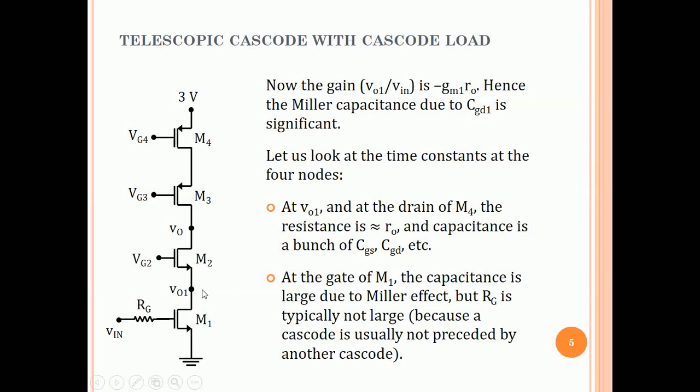How is that? So looking down again is RO1, looking up is how much? You think about it, it will turn out to be about RO. Alright, we've seen this before. In any case, so what will it be? It will be RO2 plus the resistance looking up divided by 1 plus GM2 RO2.